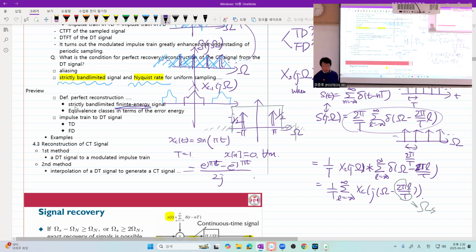And the sampling rate is here, 2 pi, negative 2 pi. So the maximum frequency content is less than the sampling rate, right? What's wrong? The sampling rate is twice the maximum frequency content. The signal is strictly band limited. Why can you not get this signal back from this signal? It's obvious, because it's an all-zero signal, and how can you get some non-all-zero signal, right?